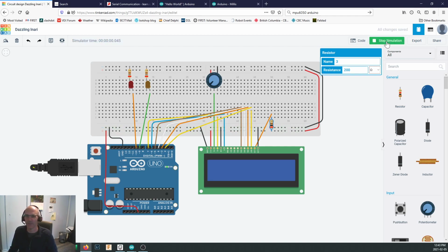And let's start that simulation now. You see the light turned on the screen? Okay, nothing's showing right now on here. Take your potentiometer and turn that contrast up. And our display. There we go. This one's fussy. You've got to turn the contrast all the way up. It should come up and say, hello world. And you'll notice that just beneath that, it's got some counting taking place.